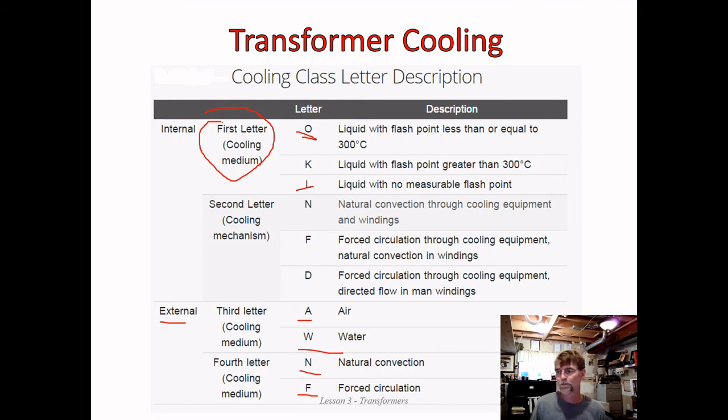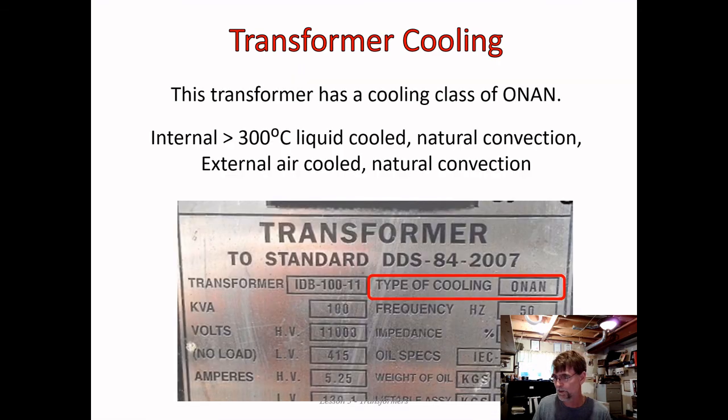Okay, so cooling of a transformer is a really big deal because primarily that's what it does. It's not going to break because of moving parts. Okay, it's going to break because it overheats and the insulation around the coil gets compromised. Okay, so heating is the issue, so cooling is important.